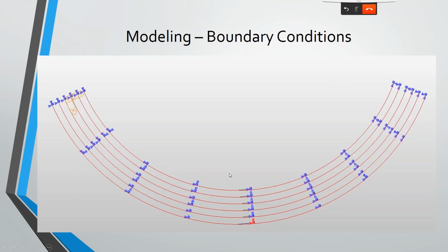Here it is from the model. You can see that there is a component on every one of them. That's because we actually put in the stiffness of every bearing. So just through the shear modulus, there is some small amount of thermal reaction. But the big thing is you're getting most of your longitudinal reactions at your fixed pier. And it's harder to see here, but most of your transverse is occurring along girder line 3.